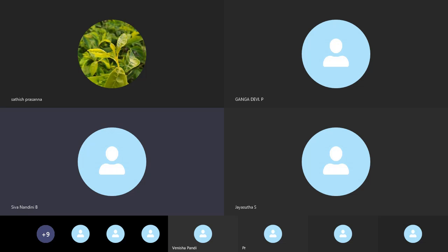With that name you choose the component and place it in the schematic diagram. Here the names given are RES for resistor, CAP for capacitor, and LM317 for that IC.